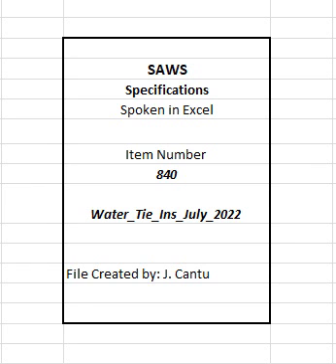14. Contractor is responsible for providing temporary water connections to critical services that are required to stay in service during the tie-in or where a tie-in duration will affect a critical service's normal operation. Advanced coordination with inspections will be required to identify critical services that could be impacted by the shutdown. 15. All tie-ins must be restrained in accordance with specification item number 839, anchorage/thrust blocking and joint restraint.